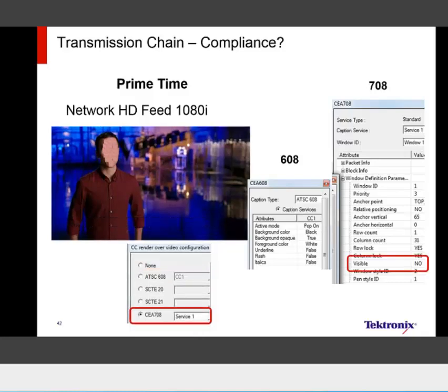We rolled to the 708 captions, same exact piece of video, and there were absolutely no captions being displayed on the screen at all. And again, this only caused issues in some customers, because of some devices grabbing the 608 payload and some grabbing the 708 payload.